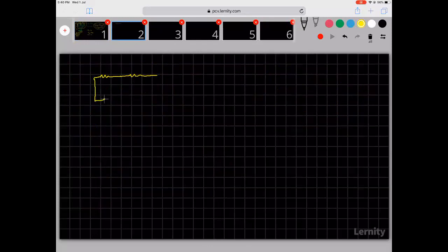Okay, so what we had there is 1 ohm, 2 ohm, 3 ohm, 3 by 2 ohm. Now, in this case, because these ratios are the same, I can say directly that these 2 points are at the same potential.